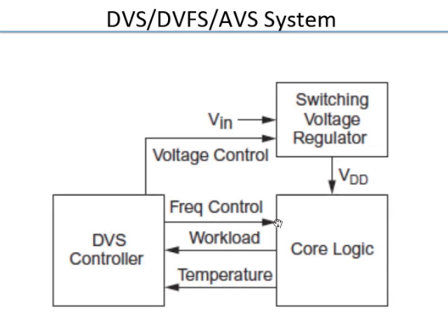It will say, okay, this is the frequency at which you need to run, and for that frequency I know this is the voltage you need to set up. So it will adjust the voltage and the frequency, so that you reduce the voltage, and hence, if there is a battery sitting outside, you reduce the energy taken from the battery. Basically, you now have closed loop systems which continuously adjust the voltage drawn from the battery.